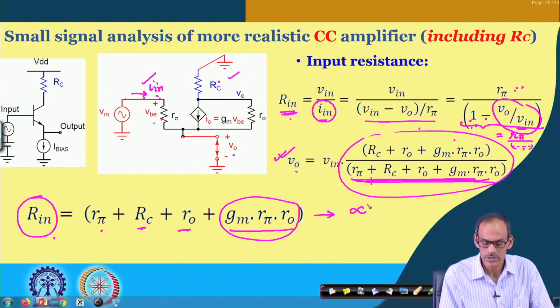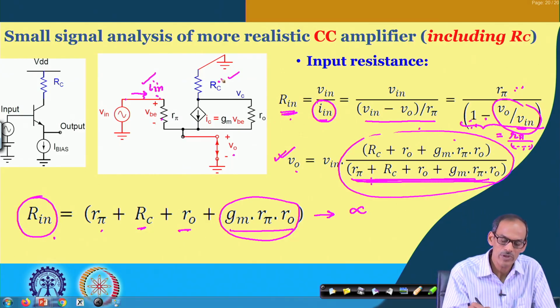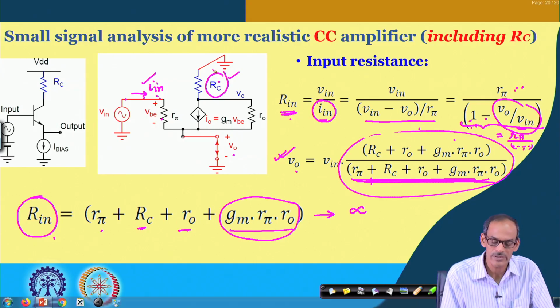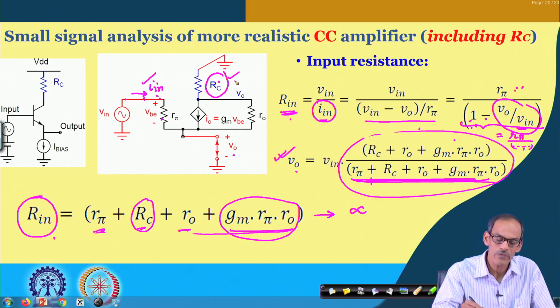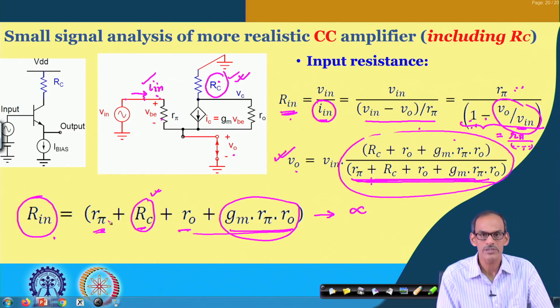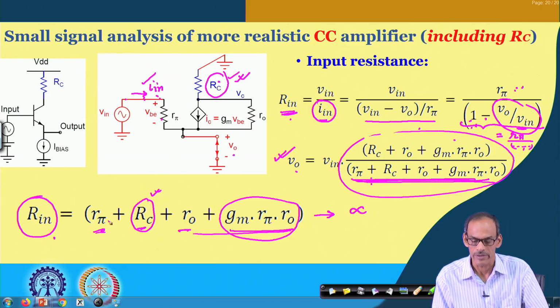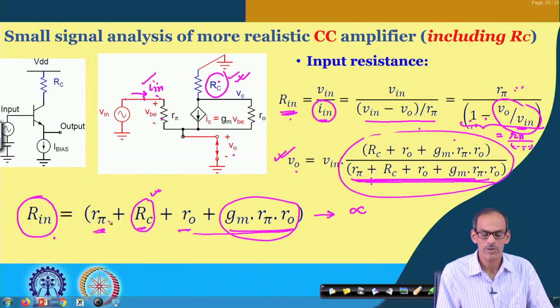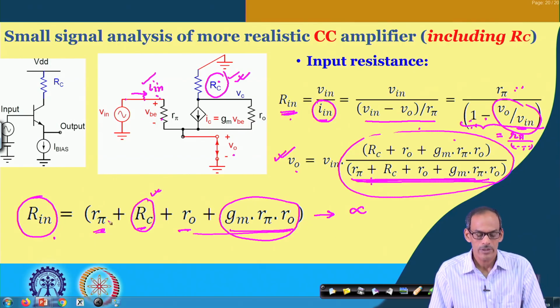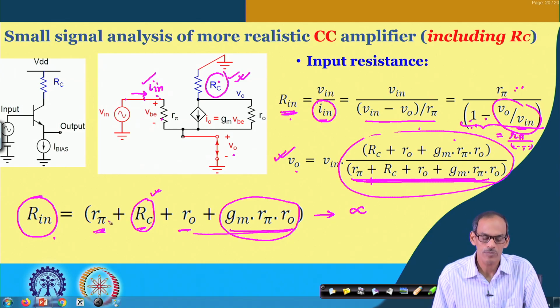It is quite obvious that since we are considering this resistance in series, it is increasing the overall resistance only by this part, and this part earlier we obtained, whatever the input impedance we are having. So, the effect of non-zero value of this R C is increasing this resistance even higher. Anyway, that is in our favor considering the required input port characteristic.